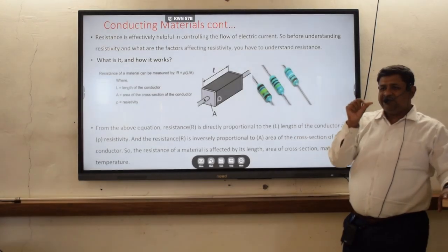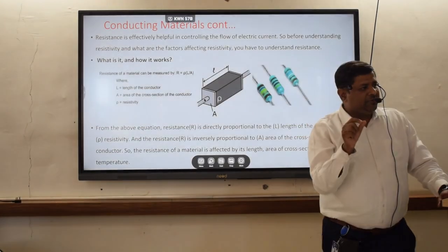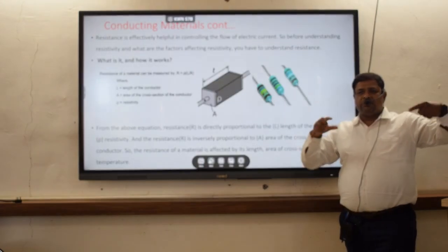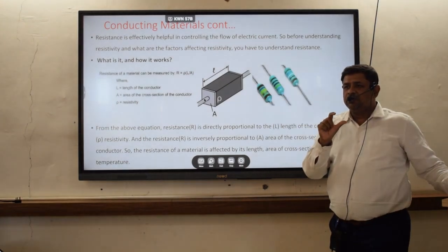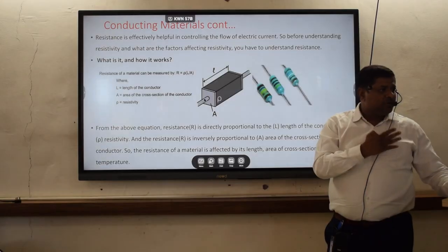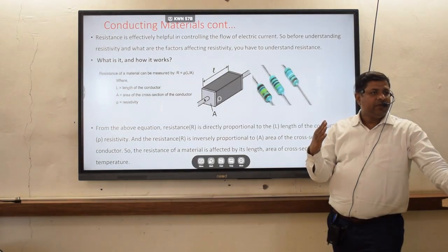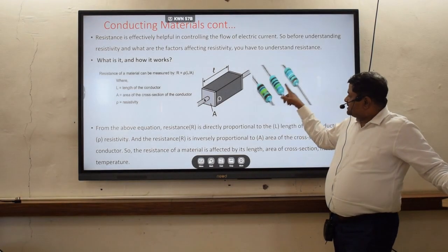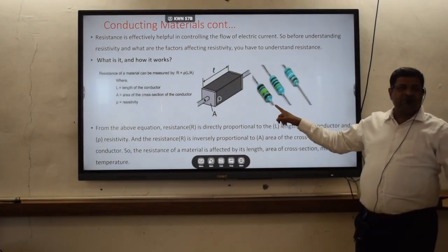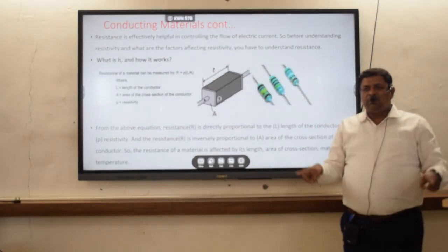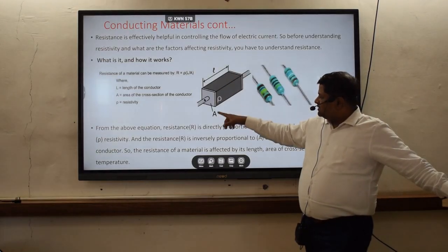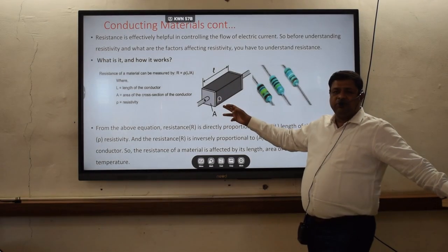capacitors or resistors in electronic devices, the small resistors are there. तो उतना लेंथ उसका ज़्यादा होता है, but उसका एरिया कम होता है. Okay, why is the area less? Because we need more conductivity. That material should pass the current. So you can see this kind of resistors on the electronic motherboard, which you might have seen. And here also you can see the length, the area and the resistivity of the material.